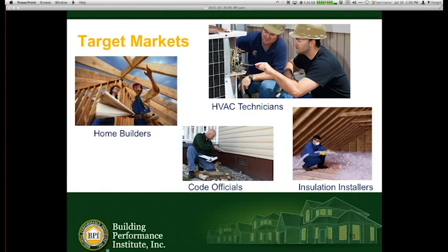The blower door is a very quick and simple test. The duct tester may take a little longer. We have a building official here in Georgia who actually felt that they should also be the one providing this. They charge the same as everybody else. They actually do the DET, which is duct and envelope test here in Georgia.